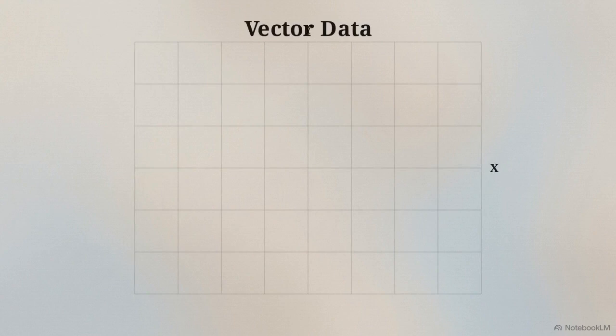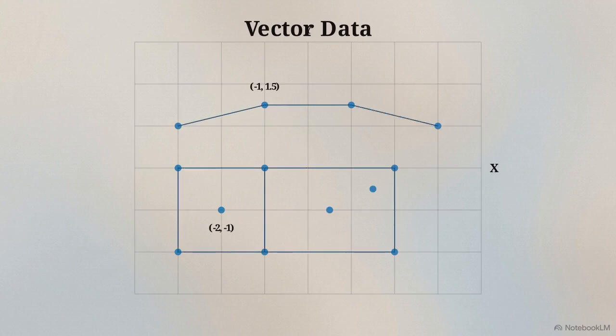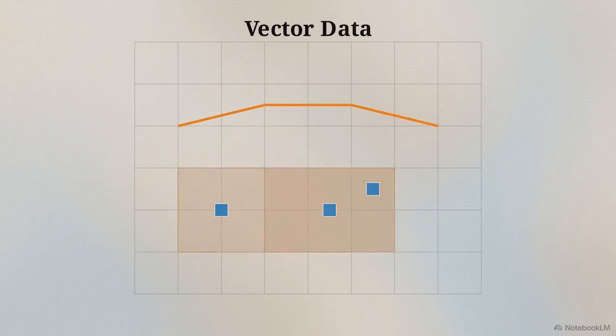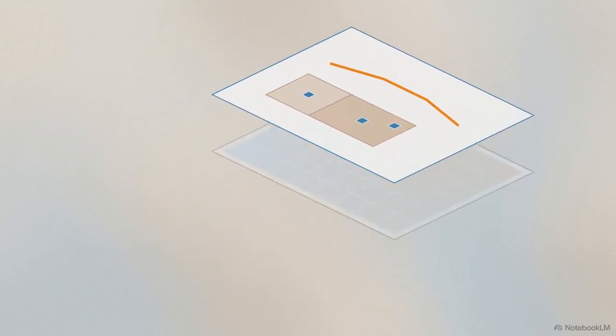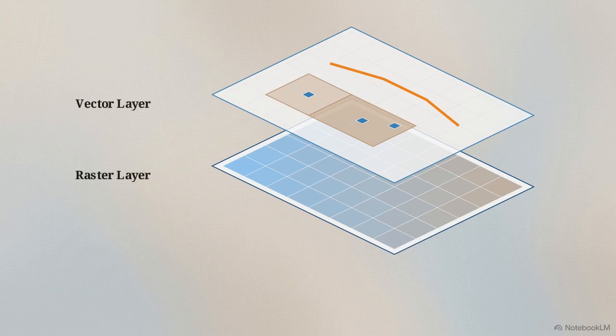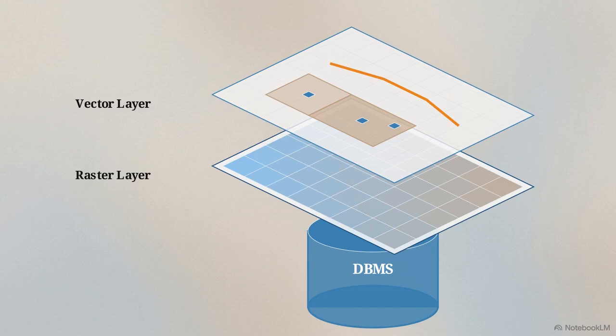Laying down this continuous raster layer gives engineers a precise mathematical understanding of how the natural environment gradually shifts and behaves. Next, we need to add a completely different type of information: vector data. Instead of pixels, vector data uses exact X and Y coordinates to define sharp points, lines, and polygons. In our dam scenario, vector data is used to map discrete features with clear, hard boundaries. We use polygons to define existing property parcels, lines to map out the highway routes, and points to mark individual buildings.